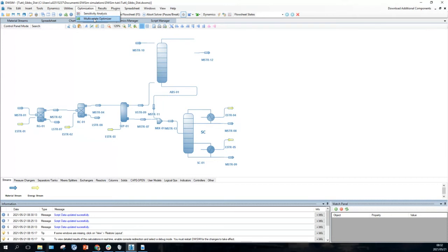Now, optimization has its uses, but then you've got to have real physical constraints to make it valid, because very often the best result is where something is physically impossible. For instance, the highest possible temperature will give you the best results on your simulation, but the highest possible temperature is not going to be okay for materials of construction.